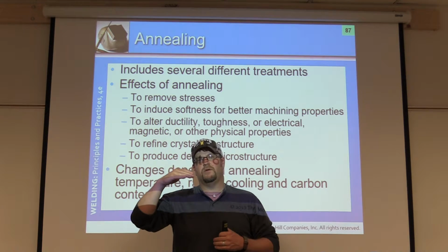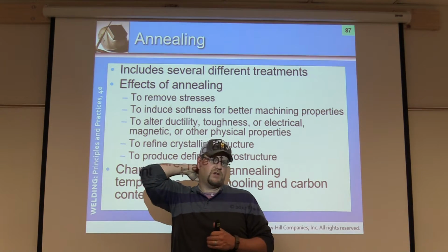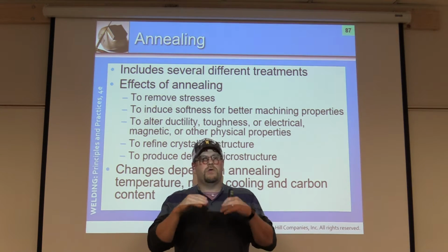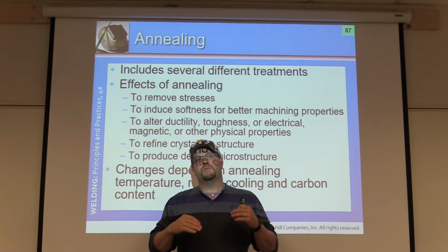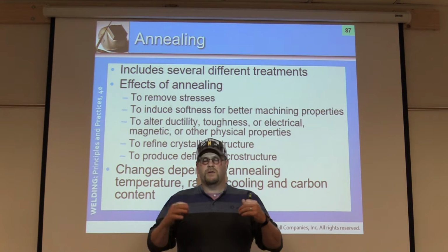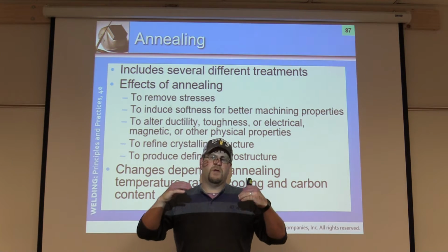So we take it up to usually about 1100 to 1200 degrees, in most procedures that I've seen done. You'll hold it there for an hour, and then cool it down 100 degrees per hour for every inch of thickness after that. So it may take 4 or 5 hours to bring it back down.